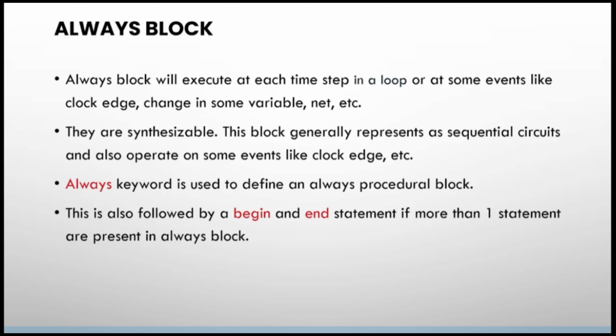Now coming to always block. It is similar to the initial block in some cases, but differs in other cases. The initial block will be executed only once, but an always block can be executed any number of times. If you want to execute it some 10 times, it will be running for 10 times based on the condition you are giving. So that is important here.